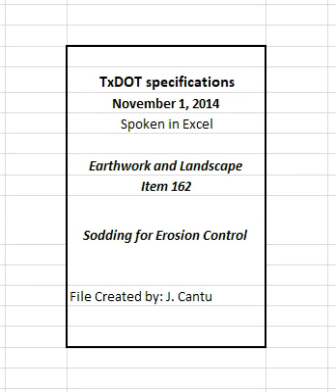2.1 Block sod. Use block, rolled, or solid sod free from noxious weeds, Johnson grass, other grasses, or any matter deleterious to the growth and subsistence of the sod. 2.2 Mulch sod. Use mulch sod from an approved source, free from noxious weeds, Johnson grass, other grasses, or any matter deleterious to the growth and subsistence of the sod.